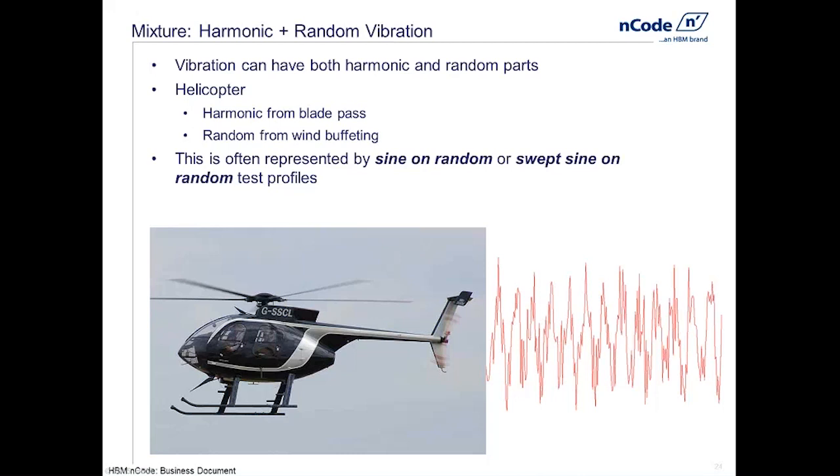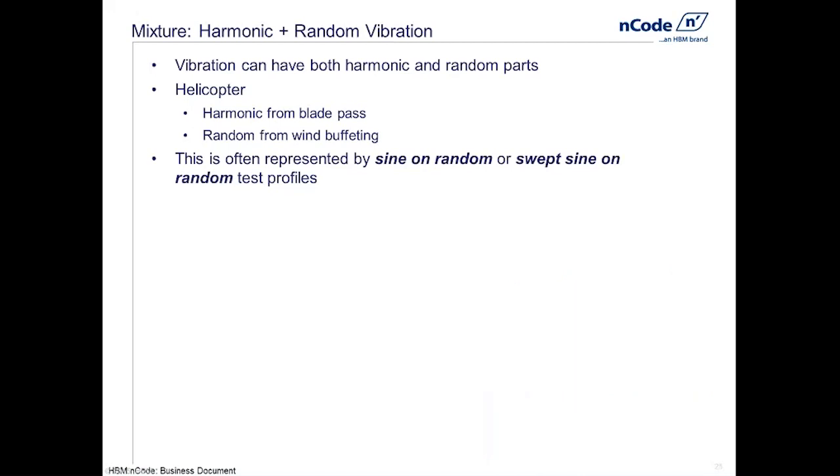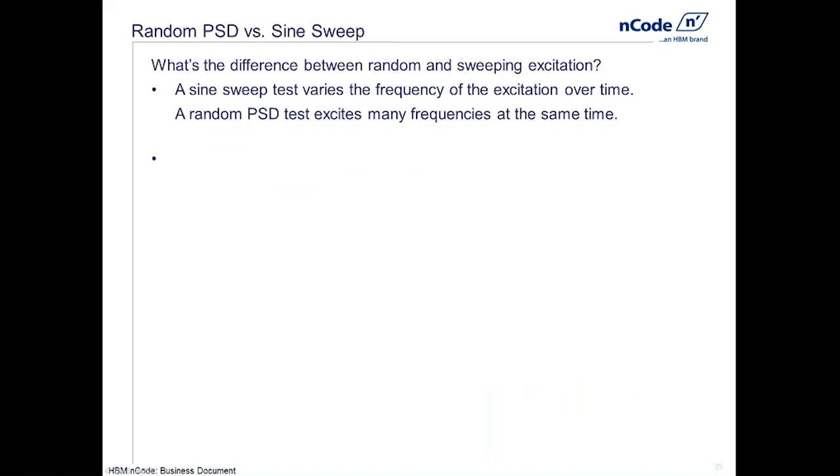So this still raises the question, though. A lot of people ask, this whole swept sine versus PSD, what does that really mean? Does it matter? I've had several people ask me over the years, I have this excitation to apply. Does it matter if I call it random PSD or swept sine? And the answer is yes, absolutely. In a physical sense, it matters. If you're running a test with random versus sweeping excitation, the stresses that would arise in the part would be quite different. If you're doing a fatigue analysis inside DesignLife, then yes, absolutely, the stresses will vary depending on whether we have random or sweeping excitation.